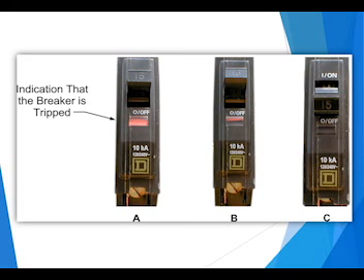There are two different types of circuit breakers that we are able to buy. First of all, we have the instantaneous circuit breaker, which only protects against a short circuit condition. And it's a very specialized breaker that's normally used only for motor circuits. We use this in a circuit with some other type of overload protection. The other type of breaker, and it is the most common type that we have, is called the time limit breaker or the thermal magnetic circuit breaker.